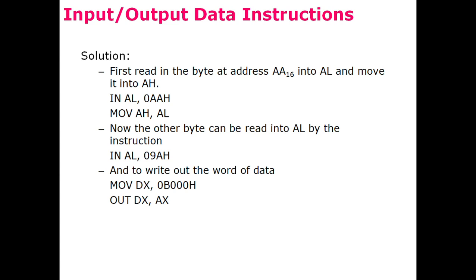So these are simple examples of how input and output instructions may be used to send and receive data from the input and output devices. All these instructions are using IN and OUT, and even if they were using INS and OUTS, these instructions mean that the microprocessor is working in the isolated mode.